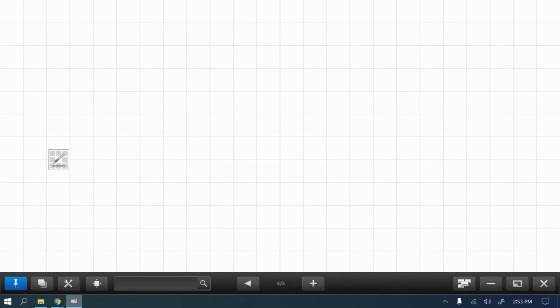Asphalt concrete surface parking. Asphalt concrete surface, no, so it wouldn't be full depth, so it's going to be the second column because it says it's asphalt concrete surface parking for heavy trucks, and I'm going to be looking at sandy, which is the first column. So what would you get? 4.5 inches. 4.5 would be your inches, and would it be like a crushed rock base? And what would your crushed rock base need to be? 0 to 4 inches. 0 to 4.